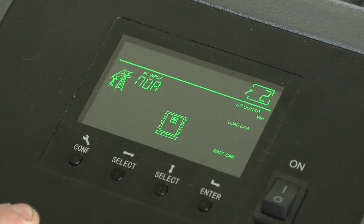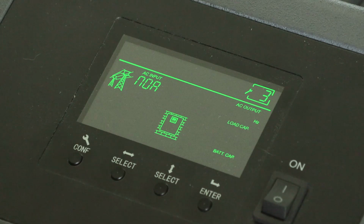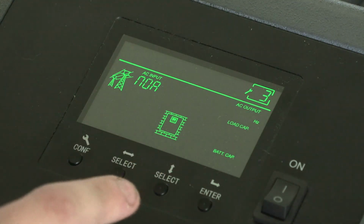Menu 2 is going to be your output voltage, which can be changed from 208, 220, 230, or 240. Menu 3 will be your output frequency. This should be changed based off the electric in your country. In the US, we are 60 Hz. In Europe, you can change this to 50 Hz.